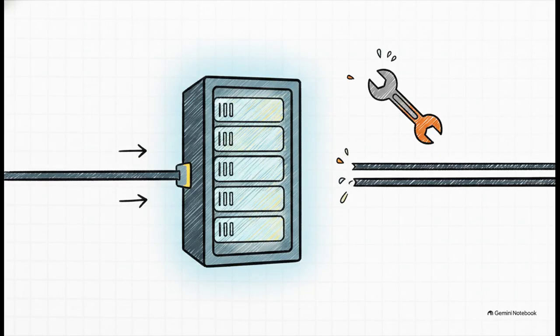The crucial answer here is concurrent maintainability. Now, don't fall for the trap of thinking it's just about slapping in a few extra generators or having some spare parts laying around. Tier 2 already has those extra parts. Tier 3 actually means you can shut down any single active distribution path for planned maintenance, and it has absolutely zero impact on IT operations. It's a fundamental architectural property of the building itself, not just a simple hardware count.